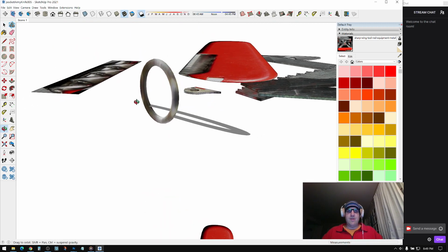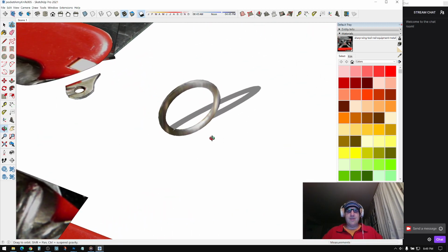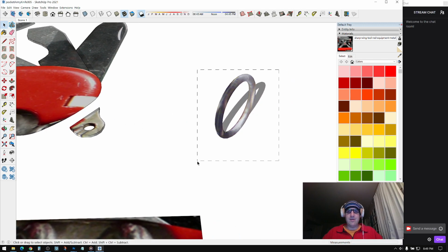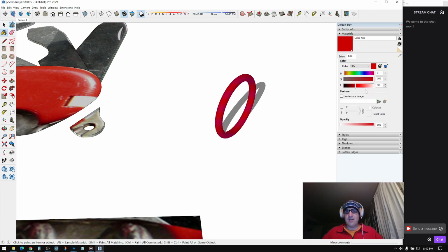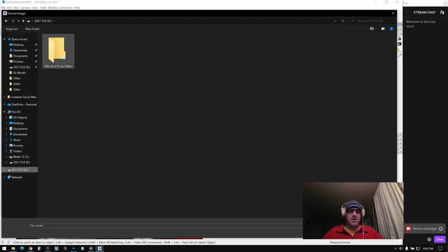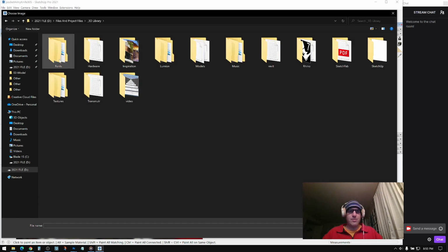Now I'm going to do something, the texture looks really messy, so on these two objects I'm going to apply a standard metal texture. So give it just any old texture, and then click Edit, in the Materials tab, click Use Texture, and in one of my other projects I made a standard small metal texture.